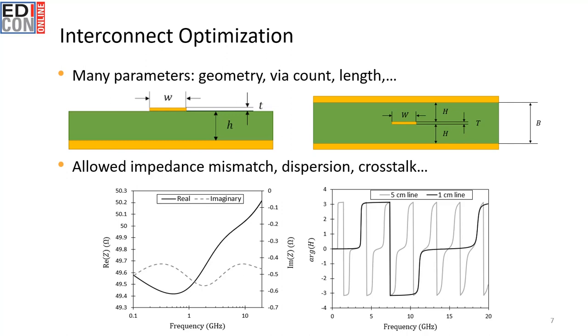But once you have this impedance curve, you can generate all the other important terms that you might need to know for interconnect design. So once you have the impedance, you can determine what the propagation constant is. And then once you have the propagation constant, you can get a transfer function, and you can take both of them and get S parameters, assuming you have a known reference impedance. So it all centers around determining the impedance and the propagation constant first. If you can do that, then you can do a lot of prediction and predict what you might measure in your channels.